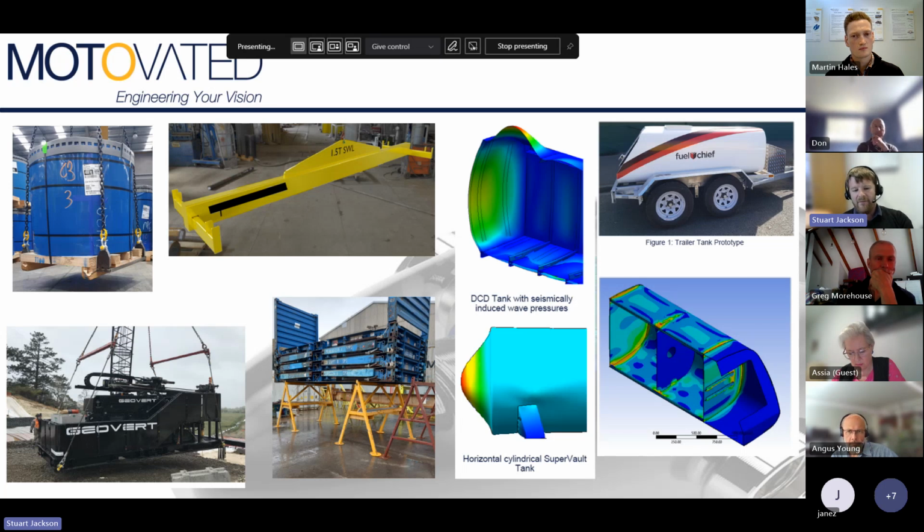And then, because we have earthquakes here in Christchurch, and we wanted to check its sideways strength, we did that by calculation. We validated those by calculation. We didn't think it was going to be very practical or safe to try and hook up a large load cell to a forklift and try and test that physically. There's a number of margins of error there. Somebody could accidentally pull the whole thing over and apply far more load. So that would be an unreasonable, impractical way of testing its sideways ability. But we can do that by calculation fairly easily with some simple assumptions.